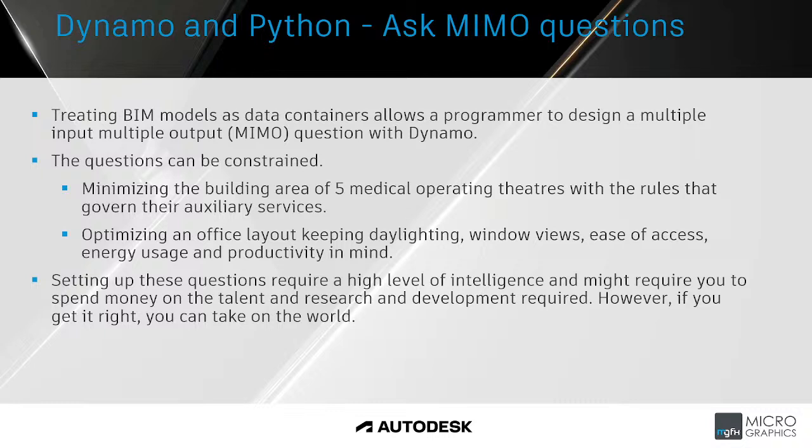And that's what makes BIM so powerful, is you've got this three-dimensional model that you can clash detect, but at the same time, you can also impart data on those elements. So treating the BIM models as data containers, essentially databases, allows a programmer to design a multiple input, multiple output question with Dynamo.